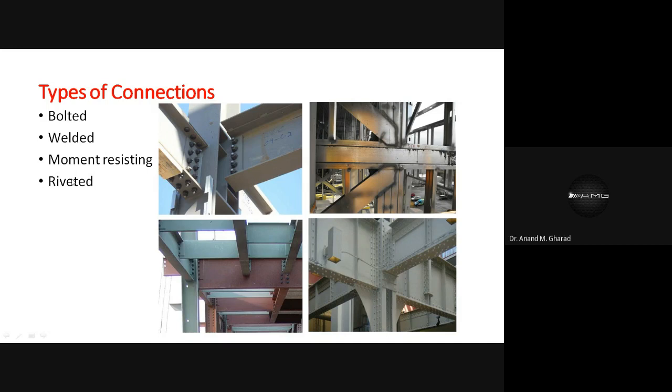Such connections are known as moment resisting connections. Those moment resisting connections may be of bolts or weld or a combination of bolting and welding, both can be done depending upon the magnitude of the moment and other force at that joint. That is a typical design that you will be studying in the elective course or in the MTech course.